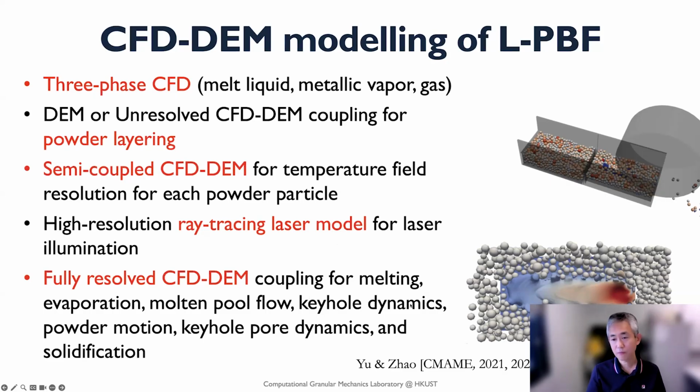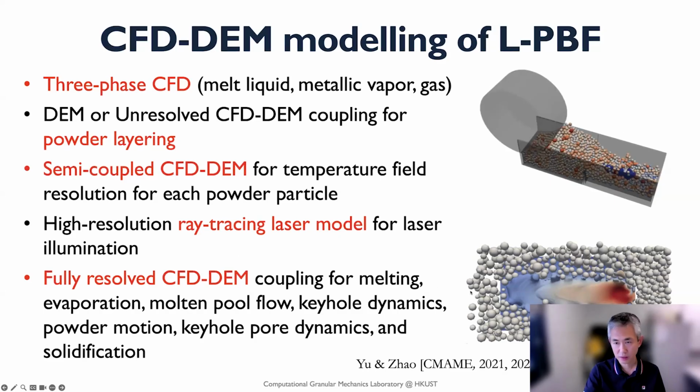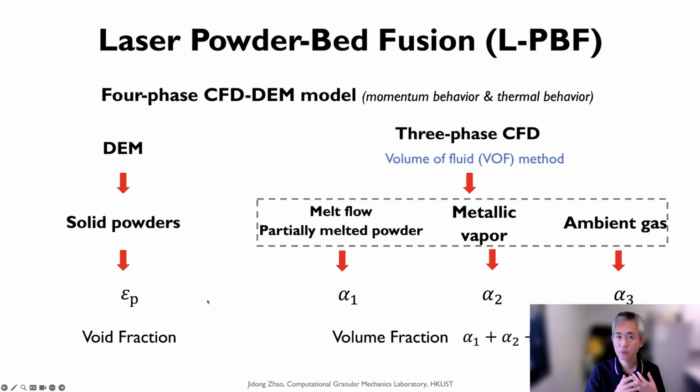Okay, and then for the following process, how the powder is melted, evaporated, and how the multiple liquid flows interact with the keyhole and the powder motion, we use a fully resolved CFD-DEM for that purpose here. Okay, so essentially this will be tackled within a very comprehensive coupled CFD-DEM framework. Let me show you how we can do that here.